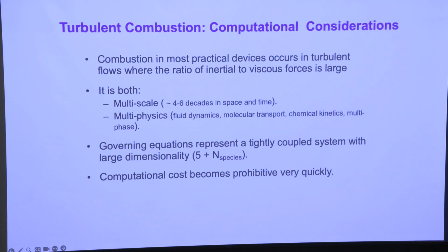So a few computational considerations. As I said, combustion in practical devices occurs in very highly turbulent flows with large inertial to viscous forces, captured by the turbulent Reynolds number. So typically we have 4 to 6 decades in space and time. So it's multi-scale, it's multi-physics: fluid dynamics, molecular transport, kinetics, and multi-phase phenomena all have to be considered. So various sub-processes that are connected.